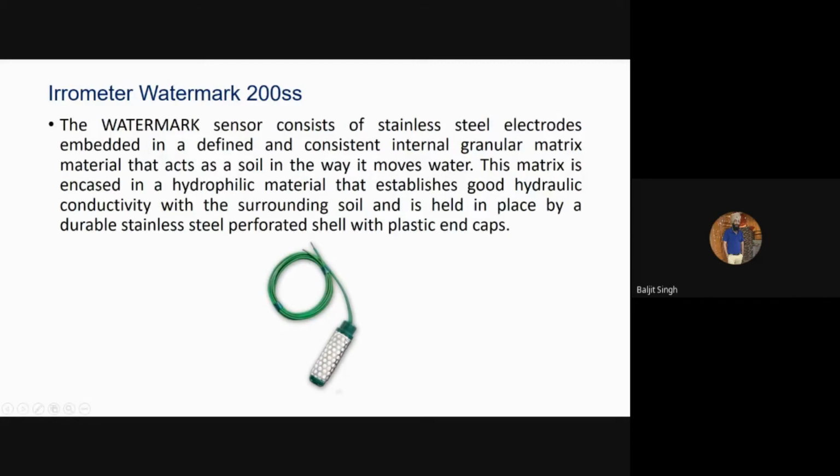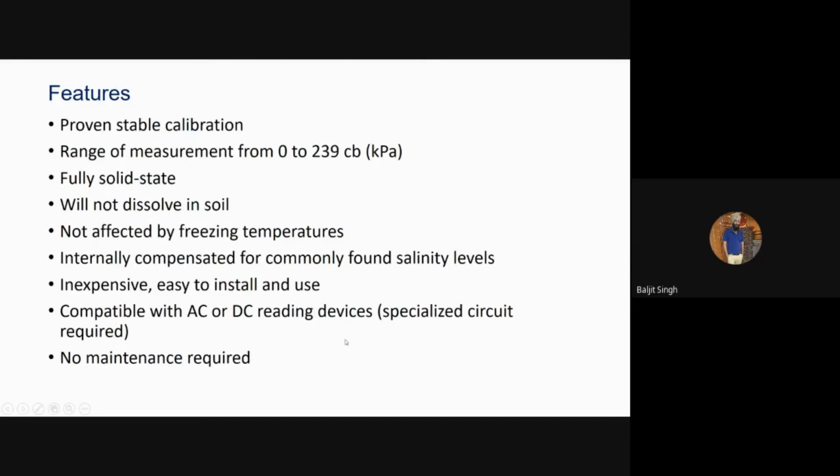Some of the features: it has proven stable calibration, a measurement range from 0 to 239 centibar or kilopascal, fully solid state, will not dissolve in soil, not affected by freezing temperature, and internally compensated for commonly found salinity levels.